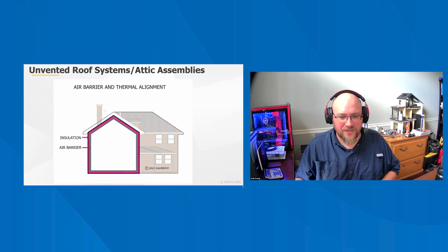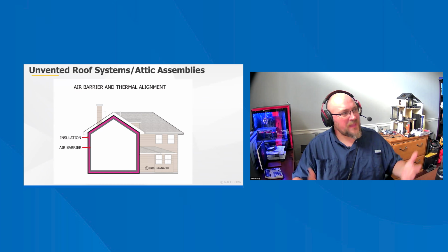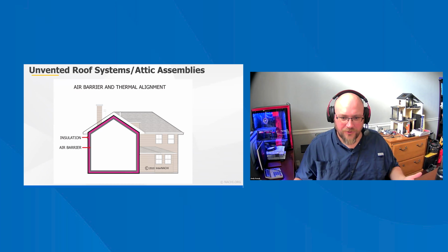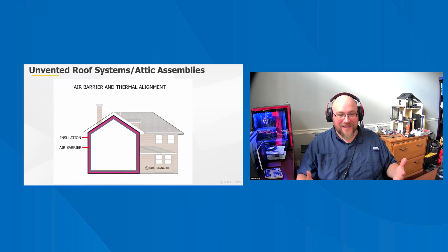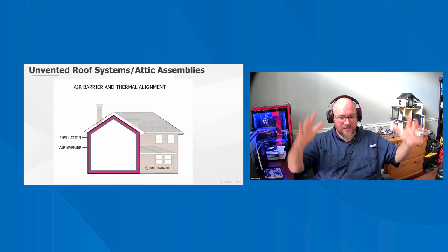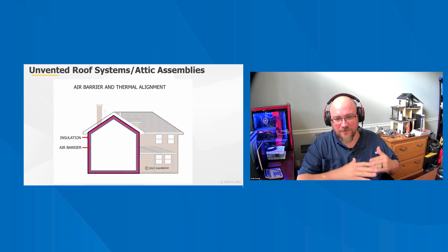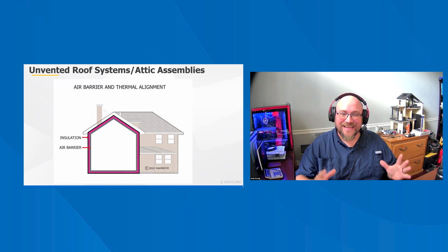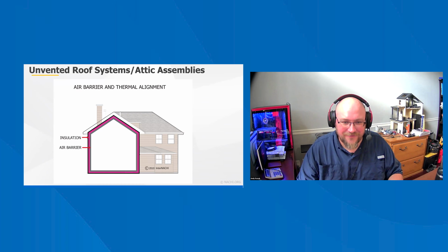Every time they would come home, they would walk into their home and all their electronics were ruined, and it looked like it had rained inside of their home. What they ended up doing, when they built that three-story addition, is they put the new metal roof over the top of the original home and the new addition. They did not change or adjust any of the ventilation.